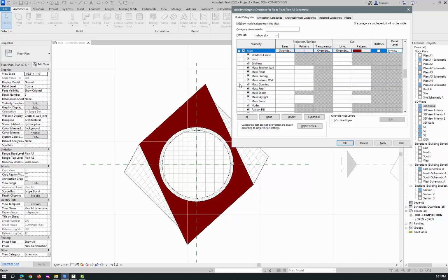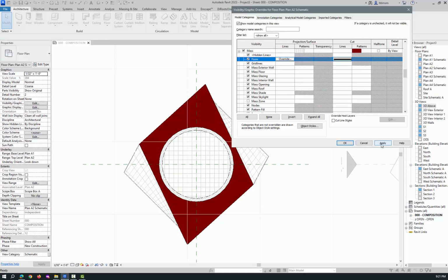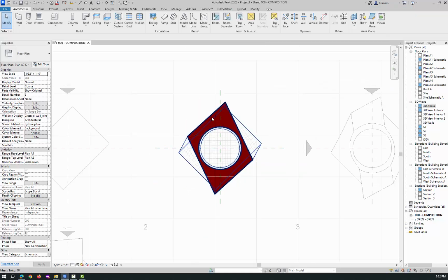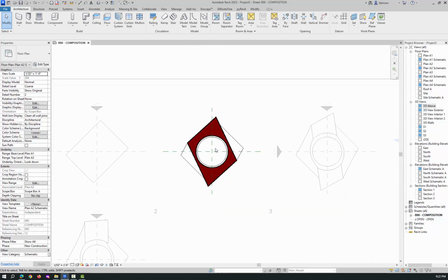You need to expand the mass and change it on the form itself. So if I come to the form and override the cut line for the form and flip that weight out for a 10 and click OK and hit apply, now I'm going to get a really thick line weight, right? So if I click OK there, now I've got that guy, and maybe I want a little bit of shadow because this looks like it's going deep down and there's a base that has a surface on it.